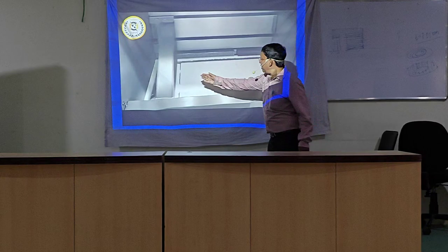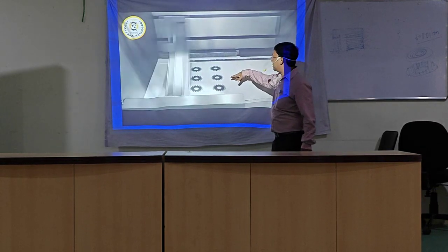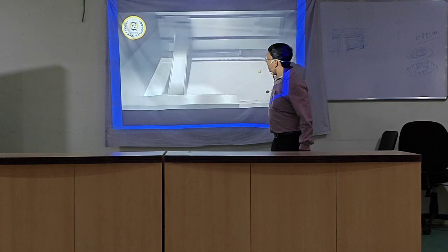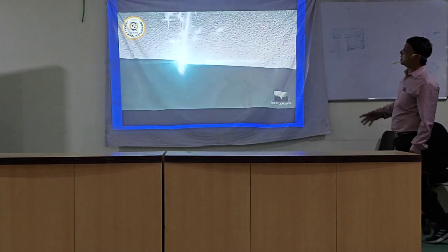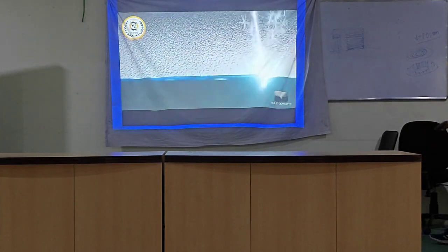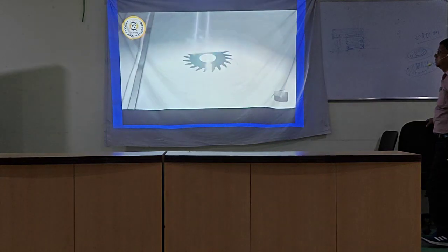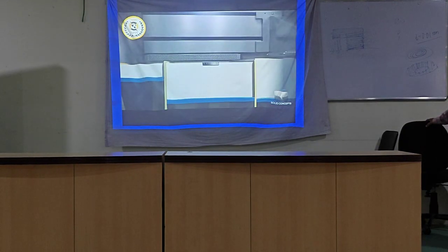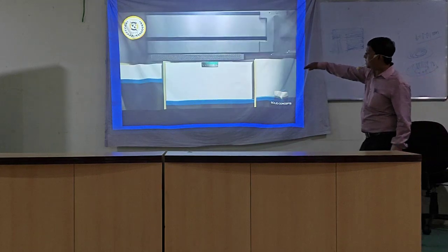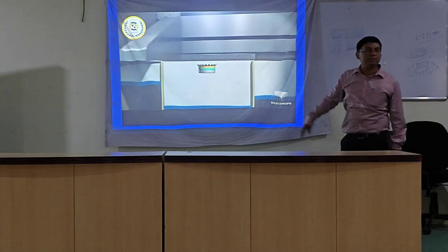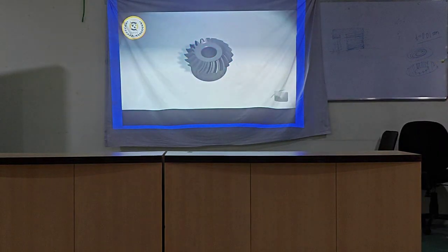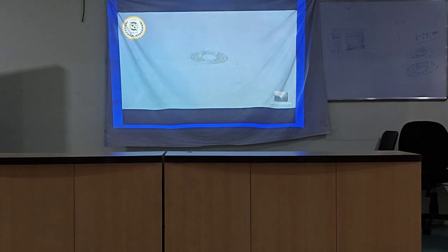This is the spreading of powder, then laser scanning, then the platform lowers down, then spreading of powder. This process will continue till the topmost layer is reached. Once a single layer is complete, spreading, laser scanning, platform lowering down, again spreading, laser scanning is repeated equally on the previous single layer. The DMLS machine continues to sinter layer upon layer, building from the bottom up.